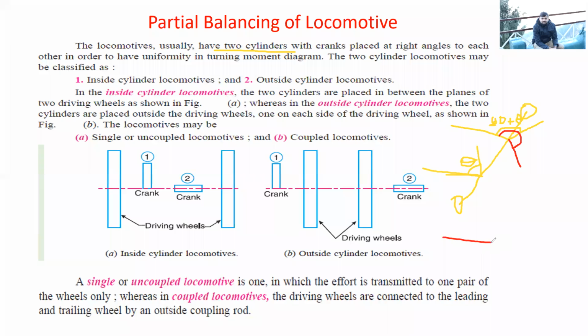One crank is like this and another crank is like this, and the angle between them is 180 degree. Once the vehicle gets locked in that toggle position, it is very difficult to remove it from that position. So to avoid being stuck in the toggle position, because then the cranking of the engine by giving so much force to the piston would have been very difficult.